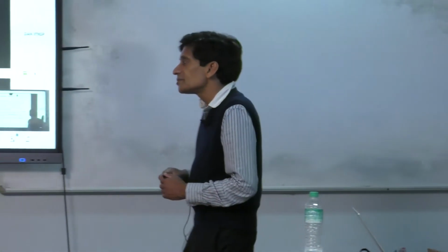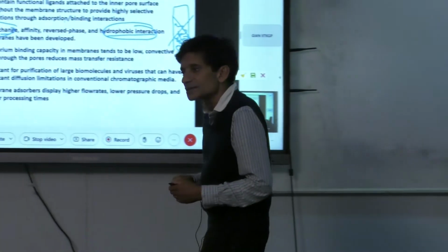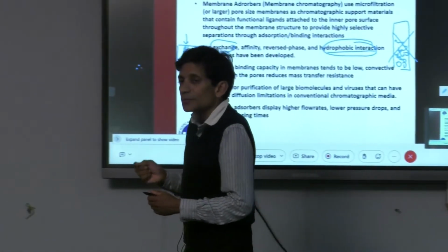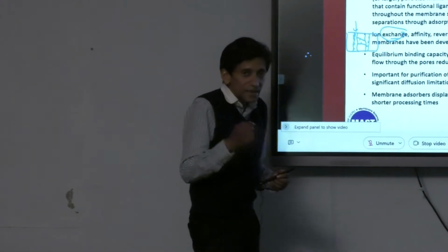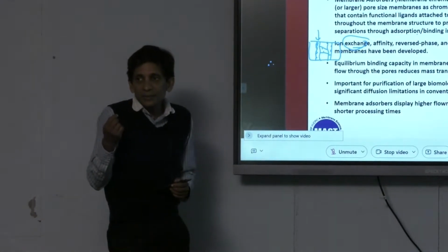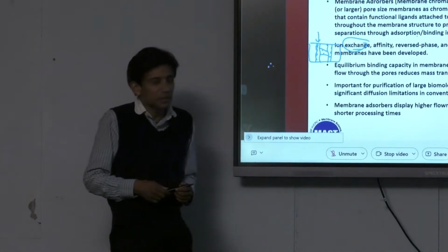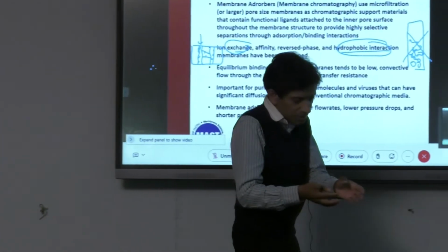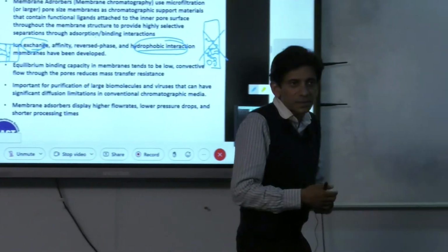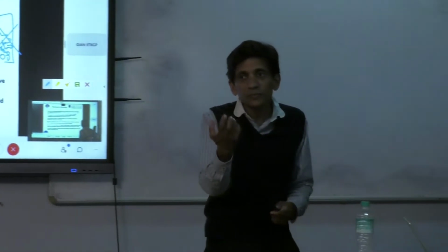This pore diffusional resistance is quite important because it's quite slow. And what happens is that it means that the dynamic capacity turns out to be a function of flow rate. So what do I mean by that? I mean, if I take the resin particles and put them in a beaker and add some BSA and have very, very slow movement to make sure that it remains a nice mixed solution, you will get static binding capacities that give you the maximum coverage.